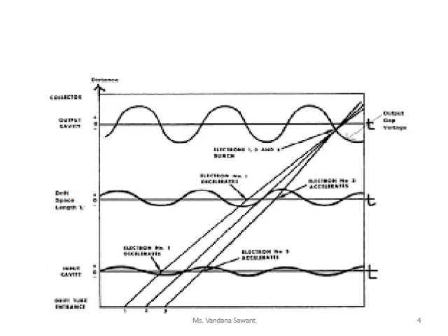Now this signal can be taken out by using any RF antenna, loop antenna, or RF probe that we can insert in the catcher cavity, and we can extract that energy, which is the amplified signal, almost 15 harmonics of the original signal. So the signal is amplified by a large amount, and we are getting it on the output side, which can be taken out and used for various devices.